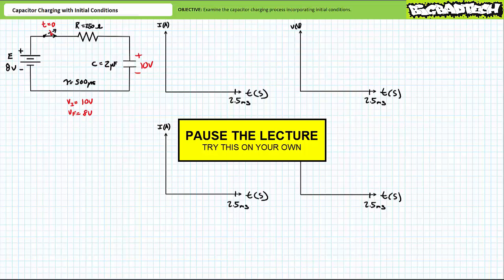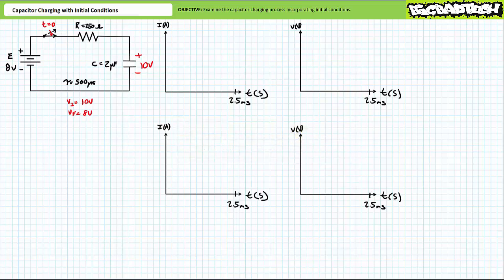If you're tracking, you should have arrived at the following conclusions. Bottom line up front, this is not a capacitor charging circuit, but rather it's a capacitor discharging circuit. However, instead of completely discharging the capacitor to 0 volts, it only discharges it to 8 volts. If you want to think of it this way, this capacitor is initially overcharged to 10 volts, and this circuit will bring it back to 8 volts. As long as you keep track of signs, all of our previous analysis techniques hold true.